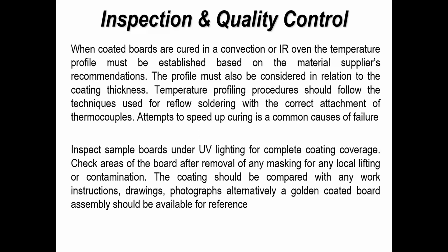But if you're using a UV material, so using a UV tunnel oven, then you've got to look at the output performance of the UV lamps. How they change over time will have an effect on the curing, and also the amount of condensation onto those lamp surfaces and reflectors. So again, you need to do the checks on the machines themselves. Again, they'll be recommended by the supplier what should be done as an ongoing process.